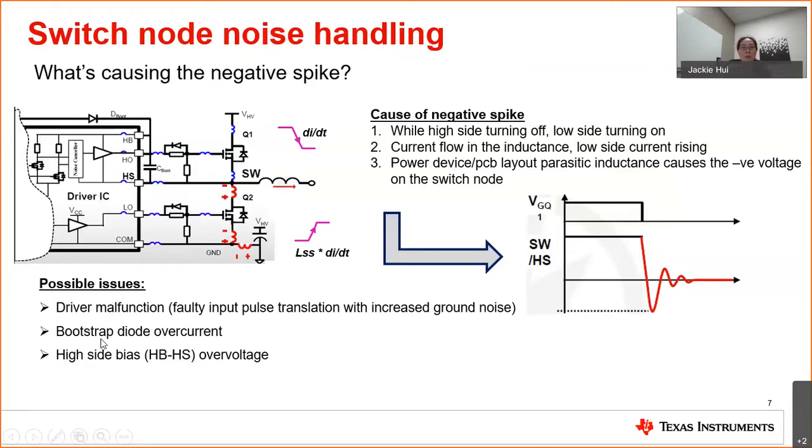The negative pulse increases the inrush current going into the bootstrap cap when it's initially charging. And for the same reason, it may potentially cause an overvoltage for the bootstrap diode as well, and this can potentially damage the driver.